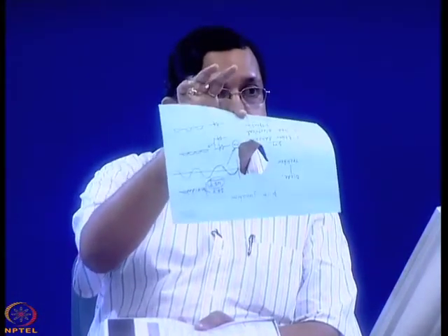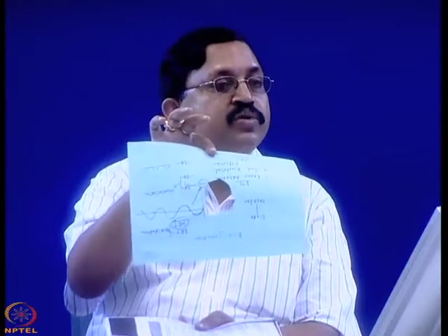if the diameter is say 4 centimeter, then the radius is 2 centimeter. So, the area of the p-n junction will be pi r square, pi into 2 square, not the whole surface. Say it is 10 centimeter by 10 centimeter or 100 centimeter by 100 centimeter, you define only the area where the p-n junction will take place, and that will be the effective area of the device. Because in many calculations, you will find a term A, area. Area of what? It is not the surface area, it is the area of the device.